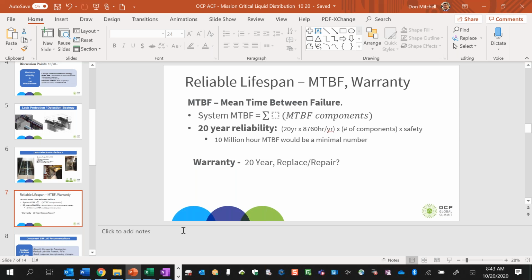Honestly, not from my standpoint, no, because we usually look at human error as our biggest factor, and we try to mitigate around human error. So take a CDU as an example. I wouldn't worry about a CDU in terms of that, because how I would mitigate it is we would put some kind of rope leak detection around the CDU that ties into the CDU's HMI, so that if there was a leak, it would shut valves or do something internally, or we would tie it back to our BMS so we can go investigate it immediately.